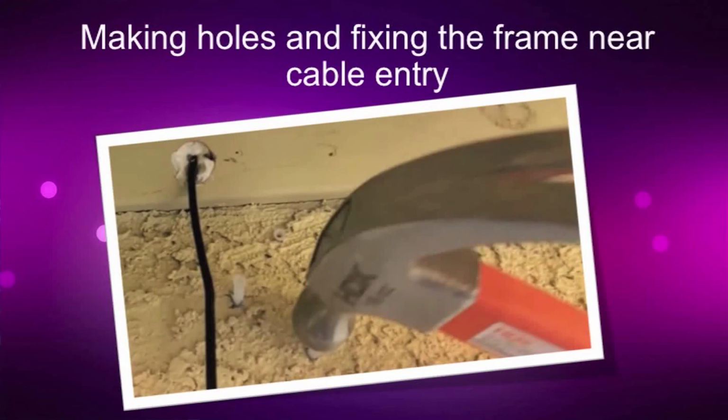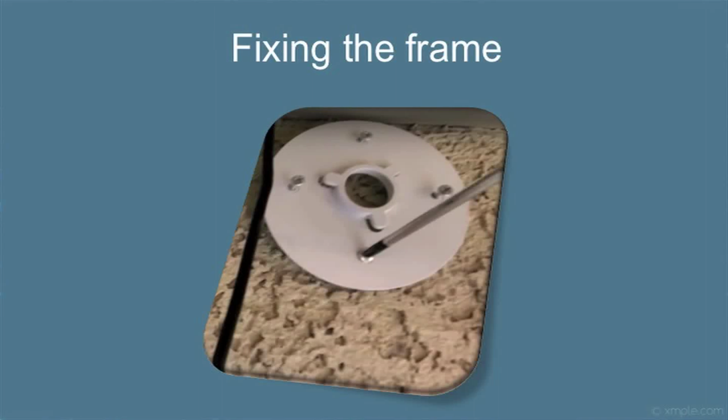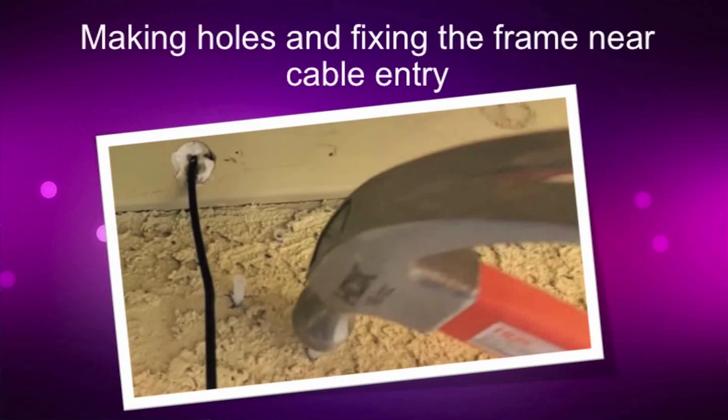Now, making the holes and fixing the frame should be done near the cable entry. This is another aspect that we need to look at as people doing the operation and maintenance of these CCTV cameras. Fixing the frame near the cable entry minimizes the length of the cable or wire that remains exposed. This is done by making the holes on the walls properly, in the real location where the camera will be mounted.